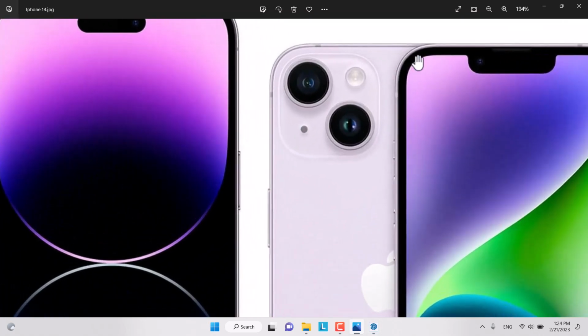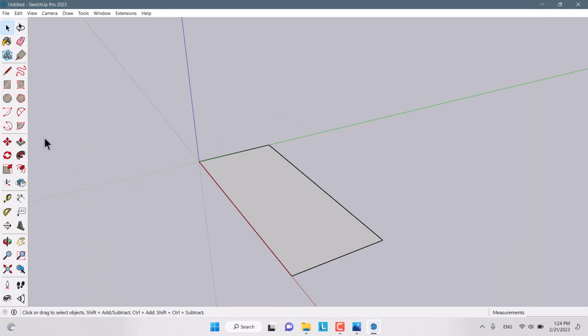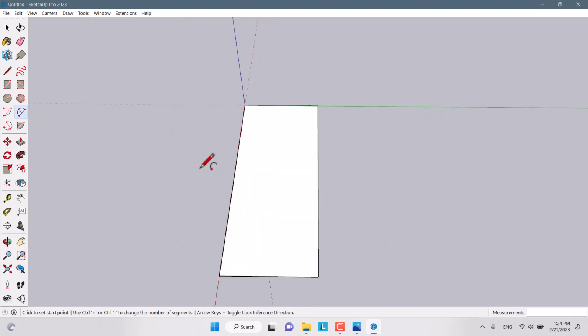You can see it's a little bit arced. In this session, you learn how to use the arc settings. One of the most important arc modes is the 2-point arc. I use it, but I don't know where I must chamfer it. So I come to the tape measure tool. From the top, I go about 8 millimeters, and from left and right the same, like that.